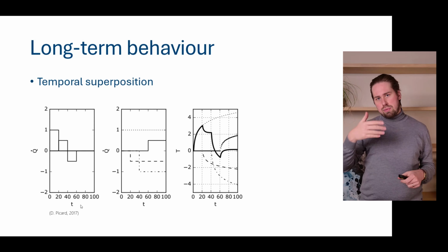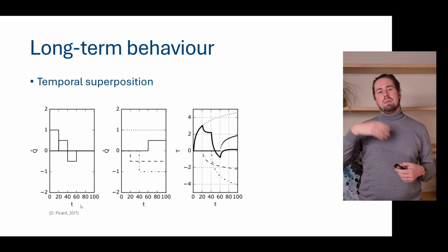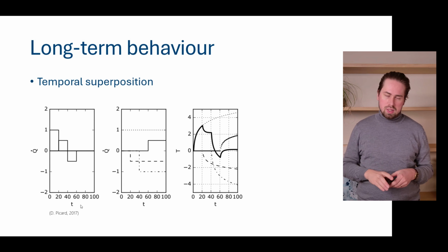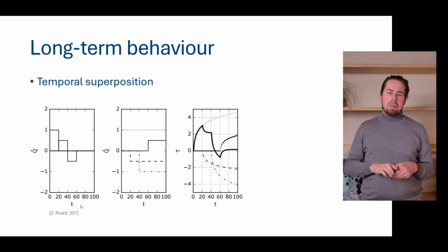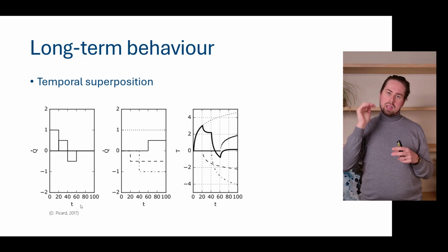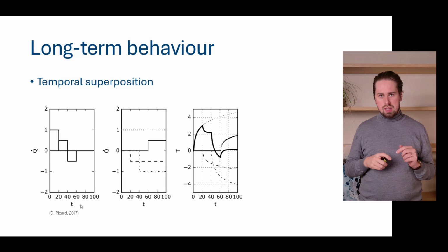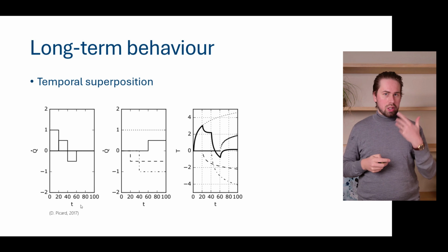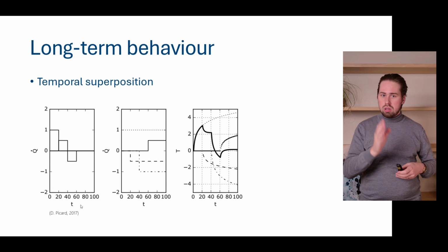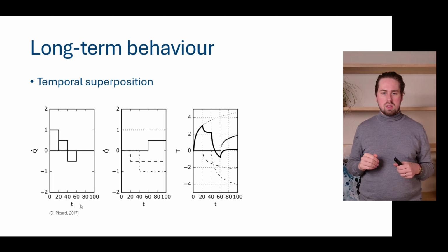And this we do for every pulse in our load. If it's hourly, we will do this 8,760 times per year of the simulation. And this is what's called load decomposition. So we decompose our load profile into constant time steps. Now, why do we care about these time steps? Well, it's because we know our G functions for every constant load. So for a load of 1 kilowatt, we know, okay, this is how our G function behaves.